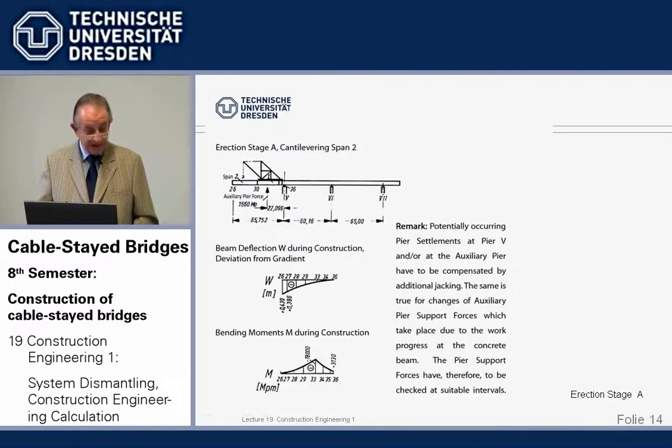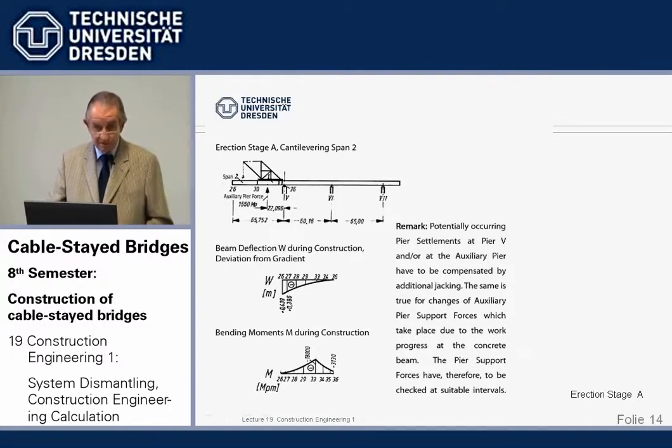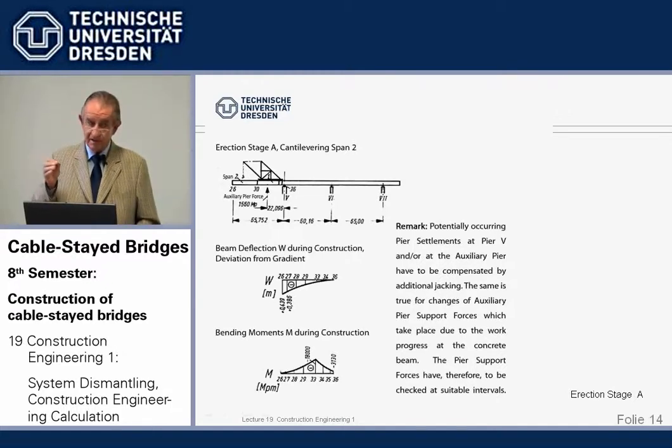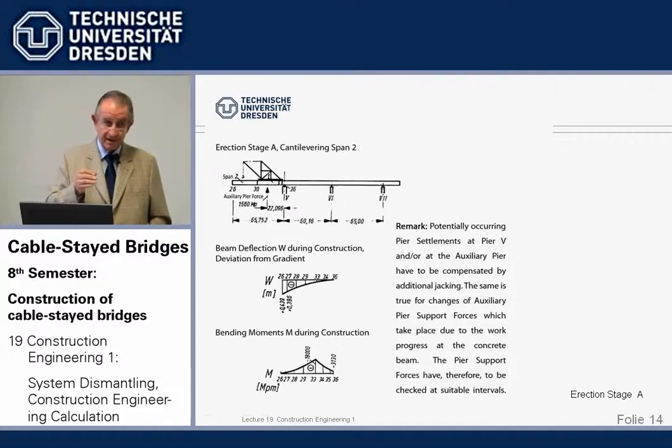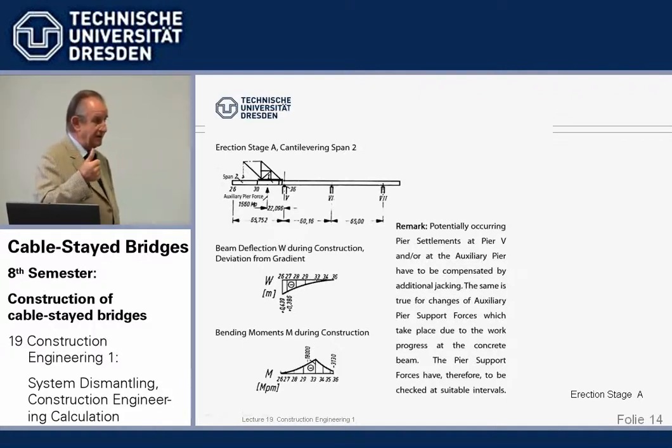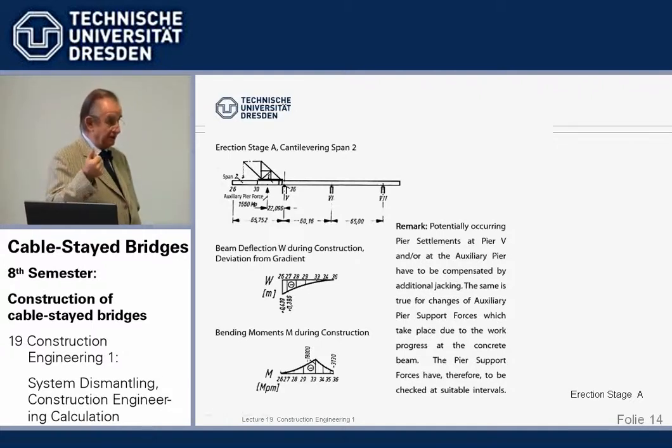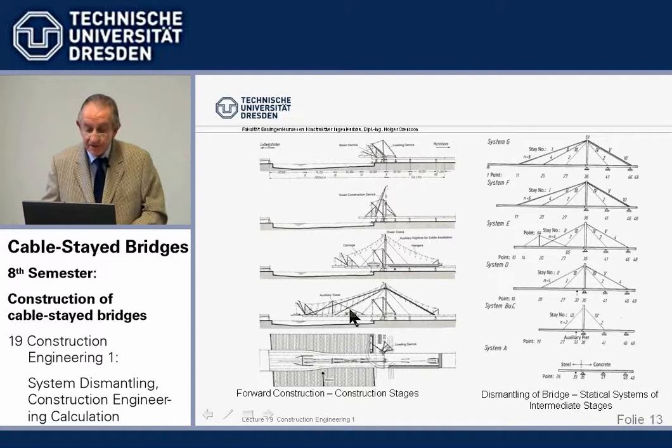And then we come to, after we have checked every construction stage, that A, it is safe, that the beam is not overstressed, the cables are not overstressed, either because hopefully the sizing for the final stage was sufficient, or in some places, hopefully not too many, we have to add some post-tensioning or steel to cater for construction stages. Only to mention, this is a typical way.